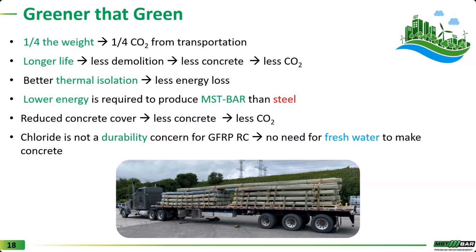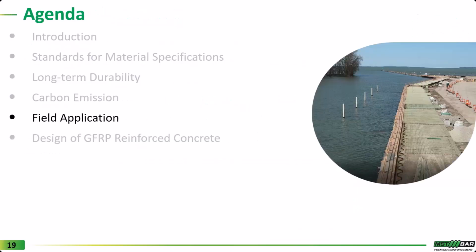Another very interesting point to mention is that chloride is not a durability concern for GFRP reinforced concrete, and this will bring a lot of opportunities to the construction industry. Now, concrete can be made of seawater and sea sand, obviously if the project has access to those materials, and there are many research studies on this subject. And also there is no need to use fresh water to cure concrete as well. So following this slide, I will show you a few examples of projects that we have completed with MST bar